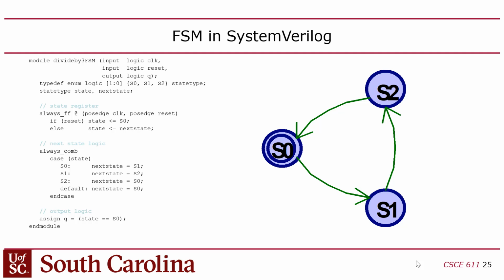And so in this case we have 3 states, but the states all have unconditional transitions to the next in the sequence. So this is just counting from 0, 1, 2, and back to 0 again. And so you'll look at the next state logic here is all unconditional. In this case, I use the case statement, though. It's fancy schmancy instead of an if statement.